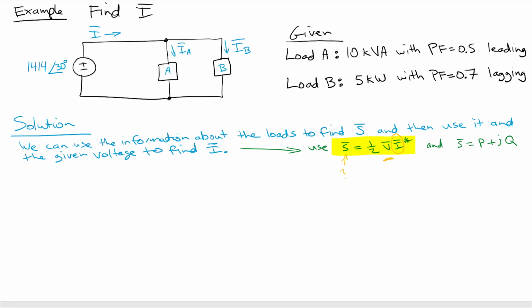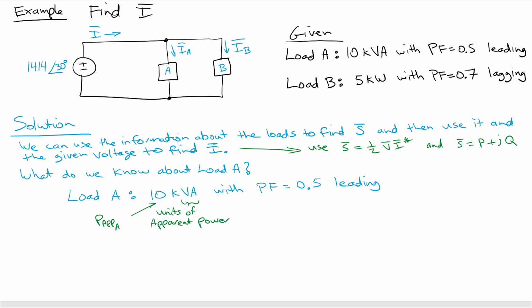Now, what else we know is we have some partial information about power. What we're going to do is solve for the individual powers, and then construct the expression for the complex power phasor, and then plug it back into here and solve for the current. So that's the basic approach we're going to take. So now let's start solving.